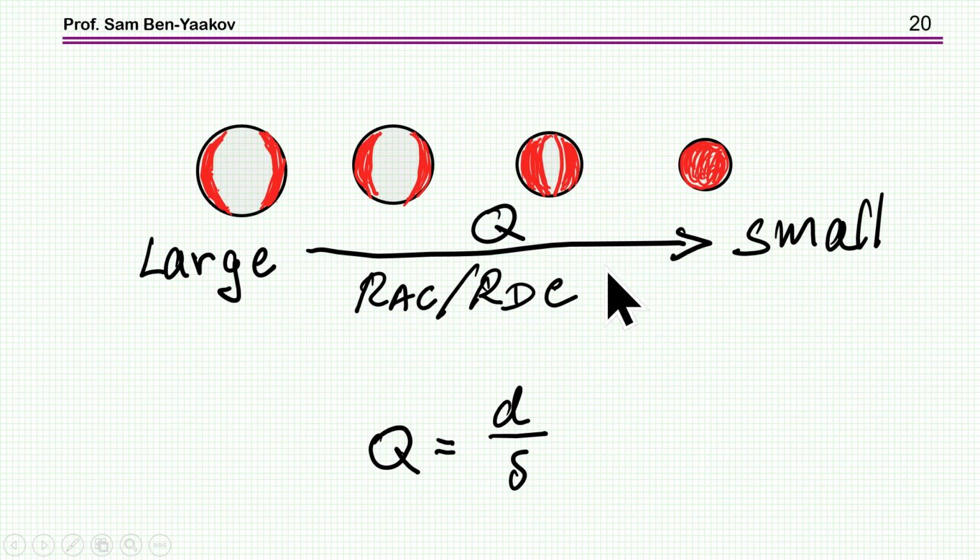So it's improving, but you have to take into account that although this ratio is becoming smaller, RDC by itself is becoming larger because you're going to a smaller cross-section area. So you can take this into account. But the point is that normally, except for some exceptions, you are not gaining anything by having an oversized diameter of a wire because the current is not occupying all the cross-section area.